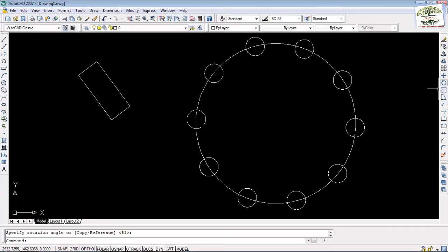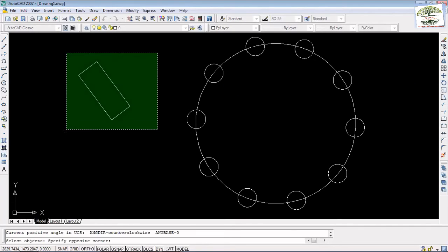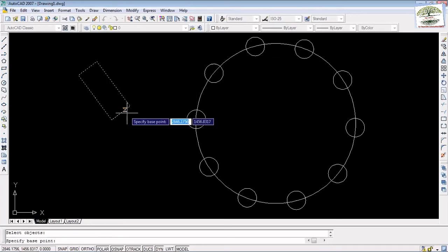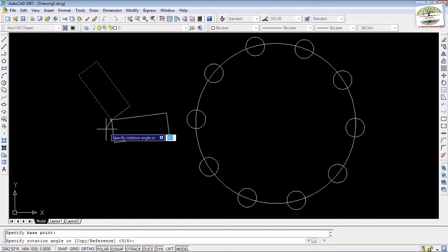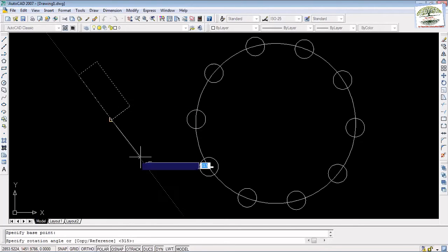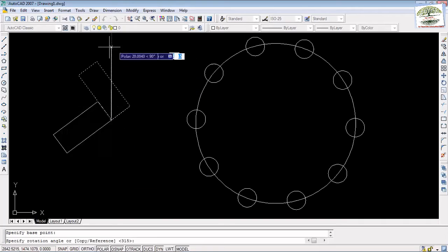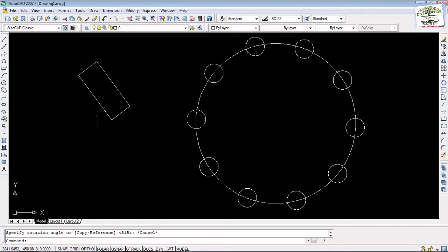It's very easy, simple. As I told you, click on rotate, select the object, right click, select the reference point along which you'd like to rotate it, left click, rotating it, done. I got my point. It's very easy. Now after rotation, we'd like to go directly to scale.